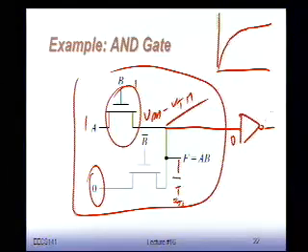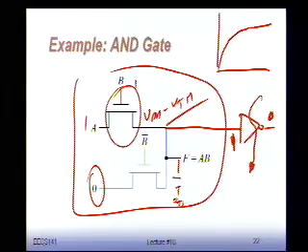Now, when you get a 0 here, this is 1. That's cool. However, when I apply VDD minus VTH here, you have a problem, because we don't get VDD, we get something which is lower than VDD. When you want to get a 1 here and a 0 there, you want the PMOS to be as off as possible. Otherwise, I get leakage current in the inverter.